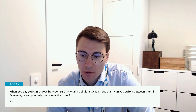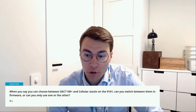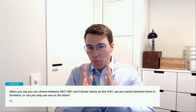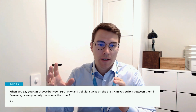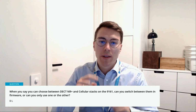When you say you can choose between DECT NR Plus and Cellular stacks on the 9161, can you switch between them in firmware, or can you only use one or the other? So in a modem, you can only run one stack at a time. In theory, you can have an external flash that has the DECT NR Plus stack, for example, and then you can switch around when you need to.